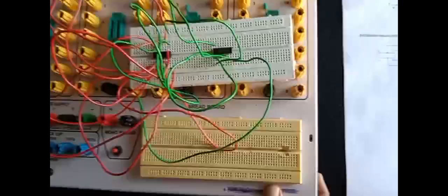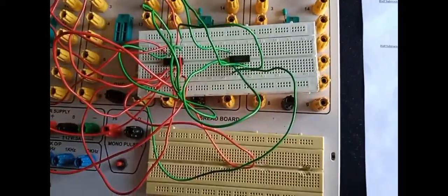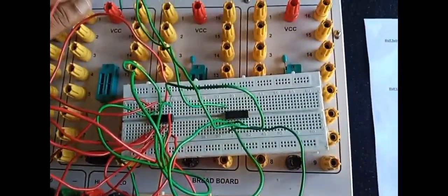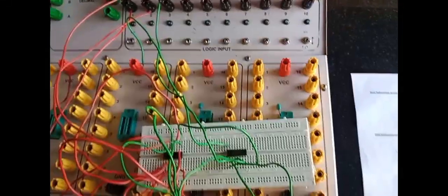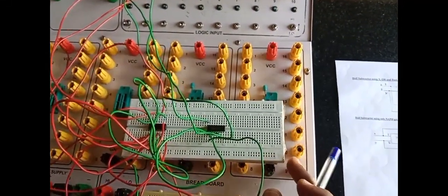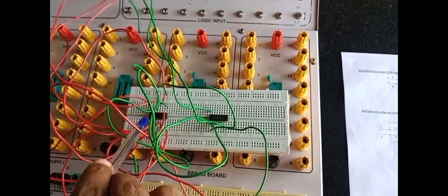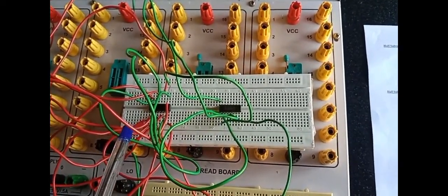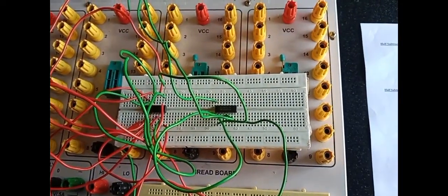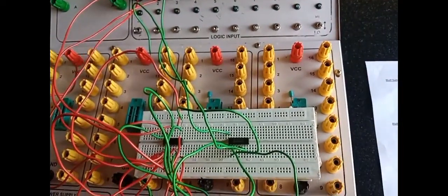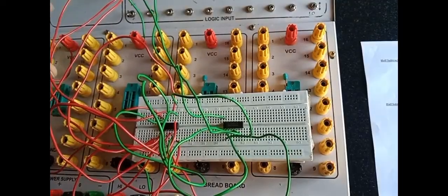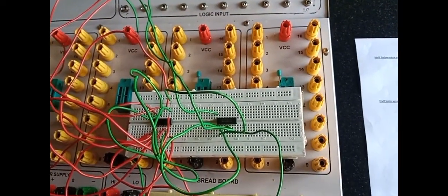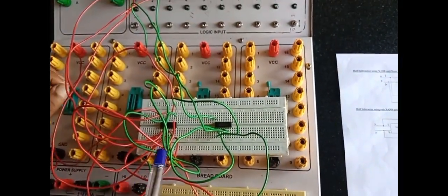So next, I am going to verify the truth table using the digital trainer kit. So this is a digital trainer kit. We give the input, VCC power supply and ground signal using this trainer kit to the IC. Here two ICs are used. So this is one NAND gate IC and this is another NAND gate IC. So input is taken from the input port. Input is given to pin number 1 and another input is given to pin number 2. So the difference output is taken from pin number 11.